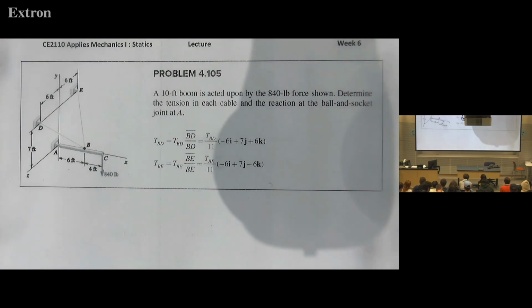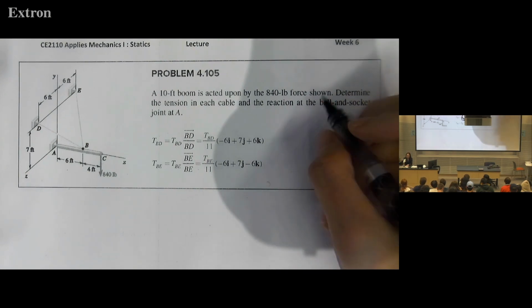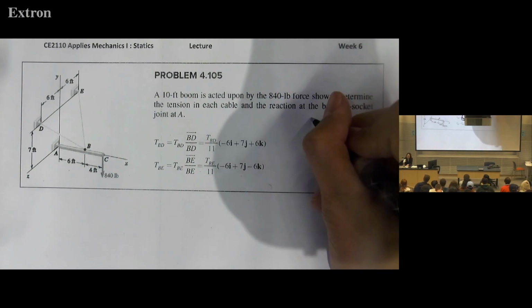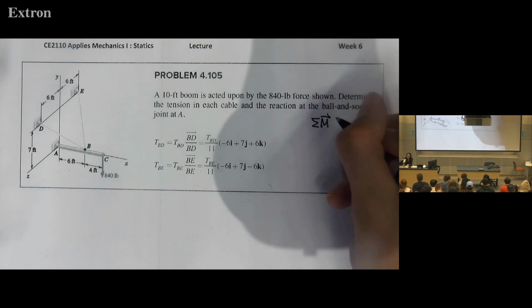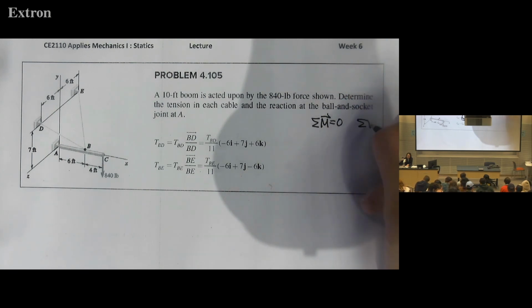So for the system, we have 6 scalar equilibrium equations. So meaning 3 force equilibrium equations and 3 moment equilibrium equations, or 2 vector equilibrium equations. Sum of all the forces, 0, so that's what we already know. And then sum of all the moment equals to 0, so that's what we will solve today, right now. Okay? So this is 3D equilibrium equation, so I'll add these 2 vector equation.